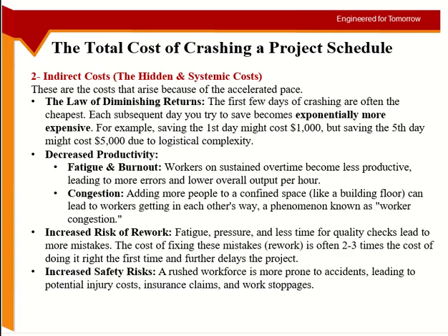Okay, and the congestion can be because of workers, it can be because of material, it can be because of equipment. Okay, so you are doing excavation. You are using one excavator. I need to finish it faster, I will hire two excavators. Does your site have enough place for two excavators to work together? Okay, this is the question.